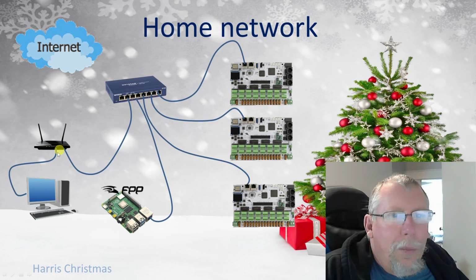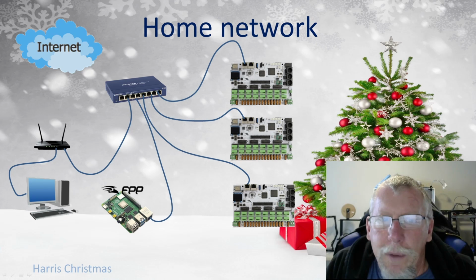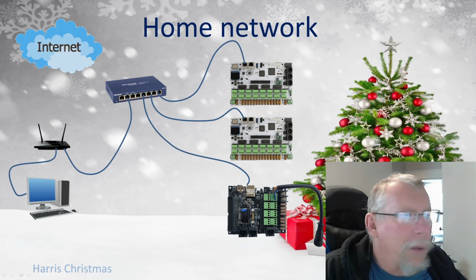Now you could also connect your computer and have it go into the switch, and at that point, if you're using xSchedule anyway, and you had the computer connected directly to the switch like this, then your show network stuff with your computer will all be isolated as well. If one of your controllers was FPP based like this, then you wouldn't need the additional Pi. You could use that as your player, and it would all communicate with all the other controllers.